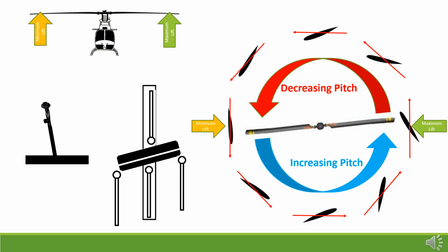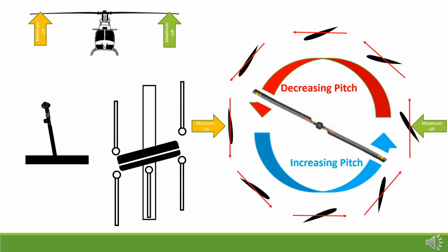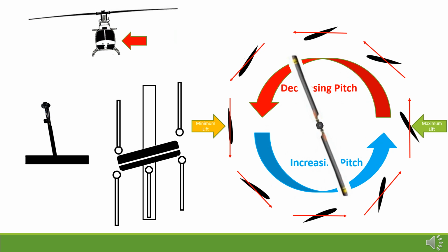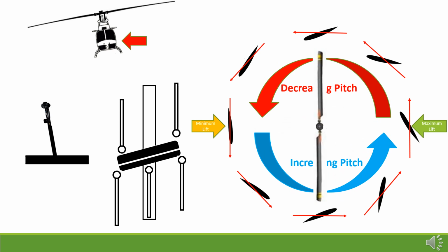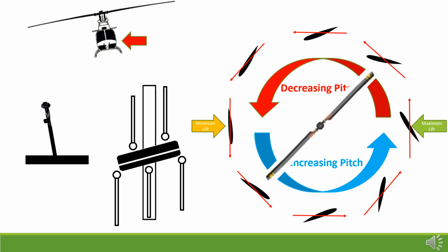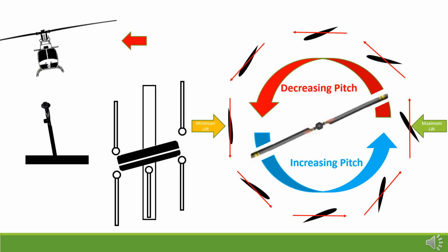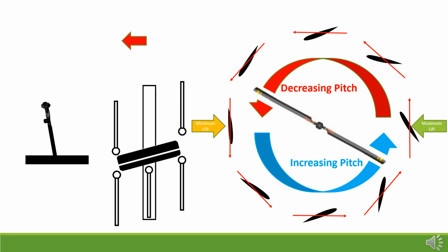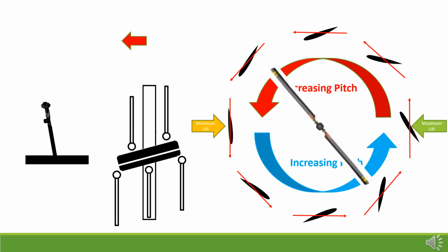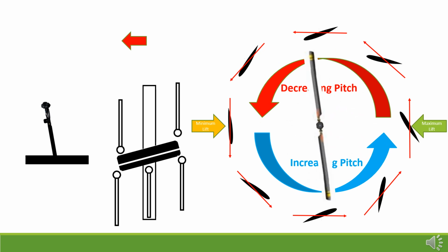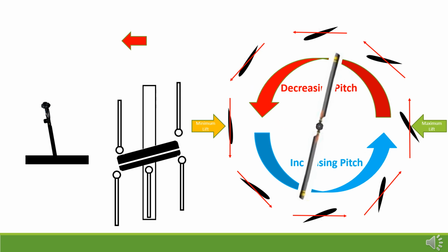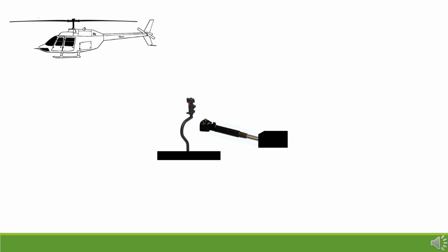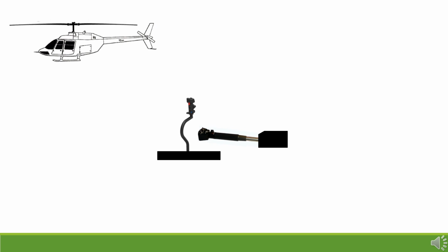When the rotor disc rotates to the right, it produces a force also acting to the right. It also makes the helicopter roll to the right, increasing rotor disc tilt and increasing acceleration to the right. Again, a corresponding increase in collective control would be required to keep the helicopter from losing altitude. To coordinate a right-hand turn, the anti-torque control must be added to move the nose of the helicopter in that direction. This same use of the cyclic and collective can cause the helicopter to move in any direction.